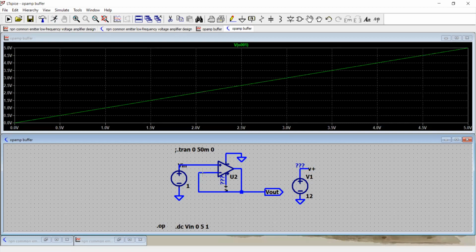Now what I want is the voltage at the negative input. Because of the very high gain of the op amp, again, let me explain to you. Because of the very high gain of the op amp, we have set it to be 1 to the power 6, okay? Because it's a universal op amp. Remember that? In the properties, you right click and see what is the property. So it is AOL, very high gain. So I will now see whether the voltage at the negative input of the op amp follows the voltage at the positive because of the high gain. So click here, right here, good.